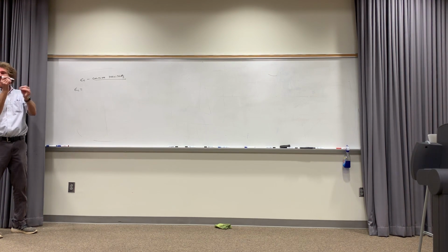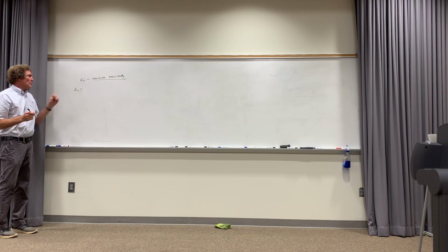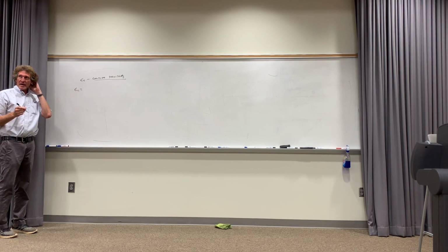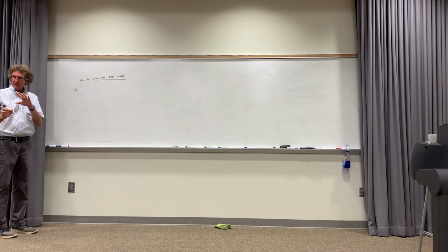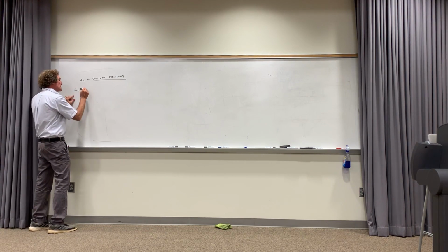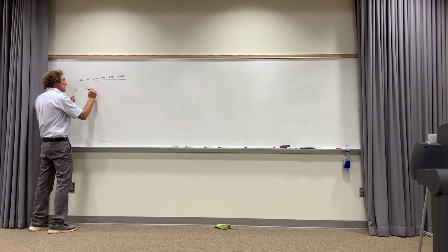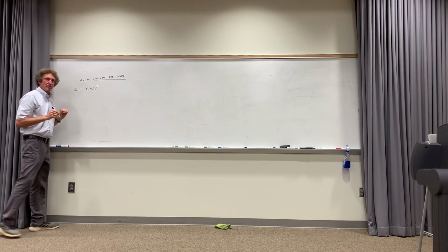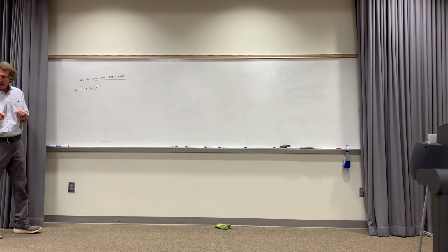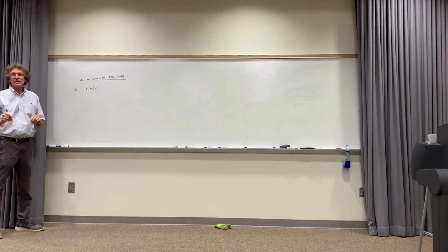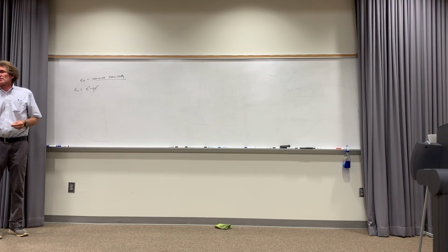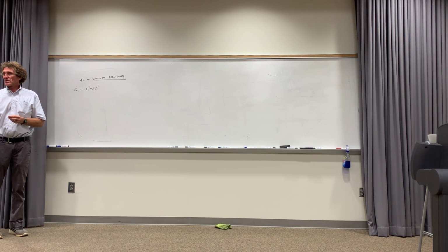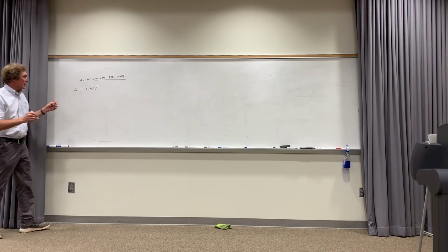So these charges can't move through. The complex permittivity will have only a real value at DC, not imaginary. But it's given as epsilon prime minus j epsilon double prime. That's how it's denoted. Now this double prime has to do with the loss, and it's just a way of really attaching a figure of merit to the amount of loss.